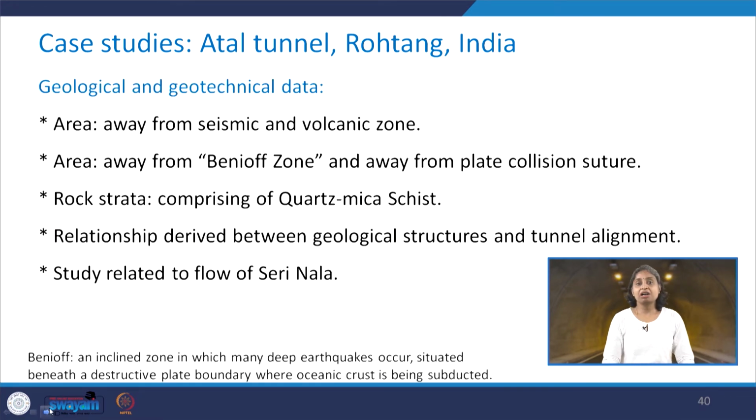So, some of the geological and geotechnical data I have mentioned here: the area of this tunnel is away from seismic and volcanic zones. Also, this is away from the Benioff zone. What do we mean by Benioff zone? It is an inclined zone in which many deep earthquakes occur, and it is situated beneath a destructive plate boundary where the oceanic crust is being subducted. So the area is away from such a zone, and is also away from the plate collision center.